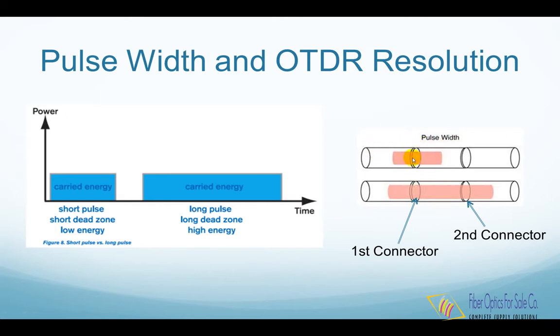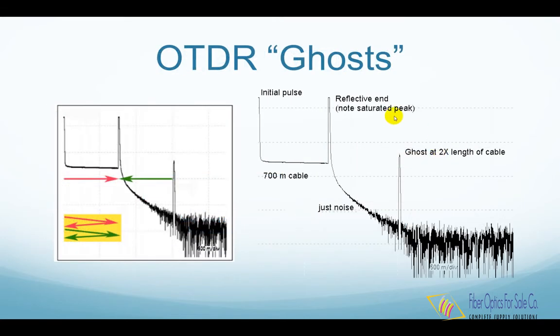If the pulse is too short, it loses its energy before the fiber end, causing the backscattering level to become low to the point where the information is lost at the noise floor level. This results in inability to reach the end of the fiber.